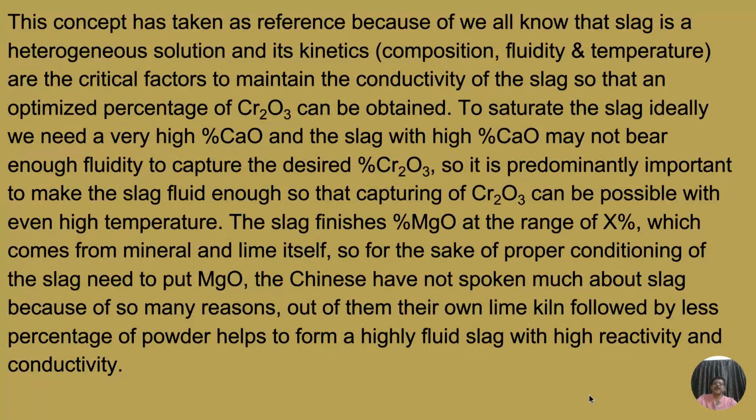The concept has been taken as reference because, as we all know, the slag is a heterogeneous solution, and its kinetics, that is composition, fluidity and temperature, are the critical factors to maintain the conductivity of the slag so that an optimized percentage of Cr2O3 can be obtained. To saturate the slag, ideally we need a very high percentage of CaO, and a slag with a high percentage of CaO may not have enough fluidity to capture the desired percentage of Cr2O3.